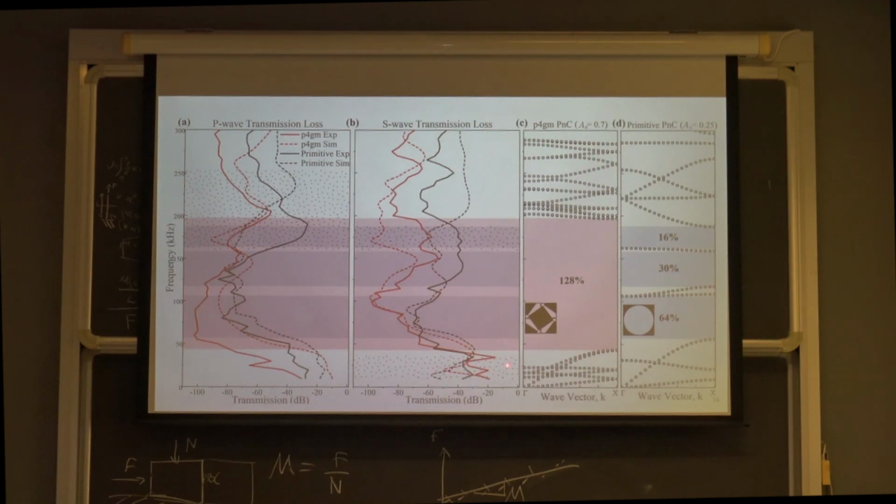How come in experiments the transmission loss is lower than in the numerical simulation? This happens because the ultrasonic transducers perform within a certain frequency range, and they have a bandwidth at which they excite well. Then there are some points where we have really weak signals, so we basically excite close to zero amplitude and then try to pick up close to zero amplitude. So that's why we cannot trust those curves. But outside of this region, we have pretty good agreement.